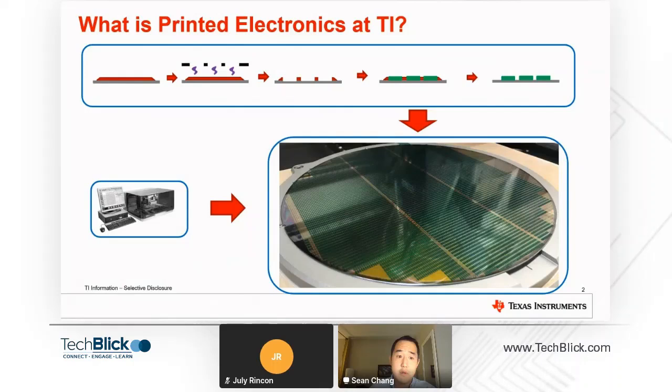And if you go from left to right, you can imagine that you've got a photoresist coat step that is then exposed with a photomask to define these patterned features in your wafer. Once the exposed material has been developed out, then you can go through with your materials deposition method of choice, strip the resist away.